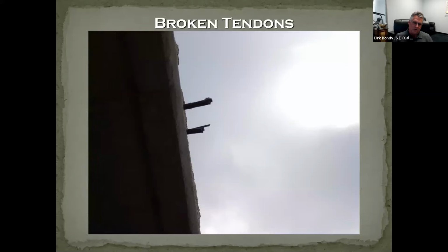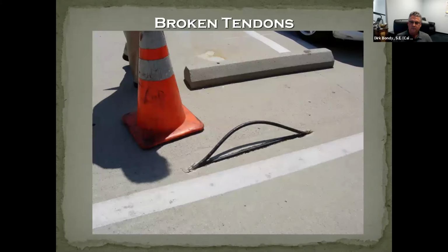Be very careful when you're called out to look at a 40-year-old building. Walk every square foot of it. Walk the top of the slab, walk the bottom of the slab, walk all the side edges and see if the concrete's trying to tell you something.